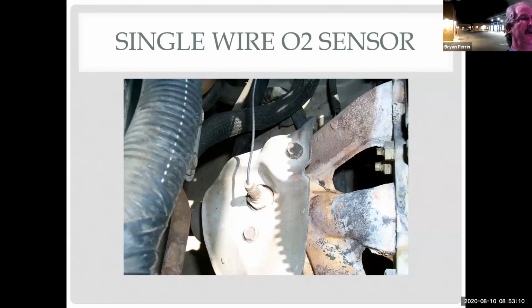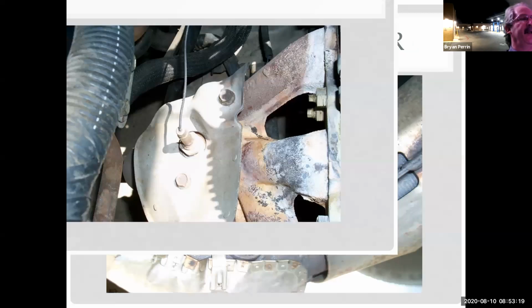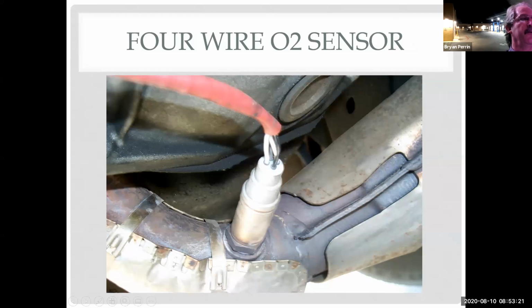And so if the outside of it got plugged up with dirt, the sensor couldn't work. So someone who went off-roading or went through the mud might have a car that ran really bad afterwards because the sensor couldn't breathe.